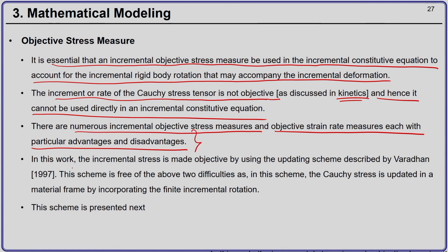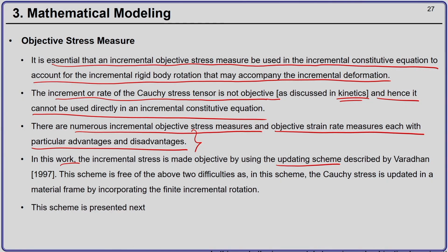In our work, we do not compute the incremental stress directly. What we do is rotate the stress in the material frame, compute the incremental stress, add it there and revert it back. We will discuss it later. So rather than an incremental stress computation procedure, we use what is called the updating scheme. The incremental stress in our work will be made objective by using an updating scheme described by Varadhan in 1997.